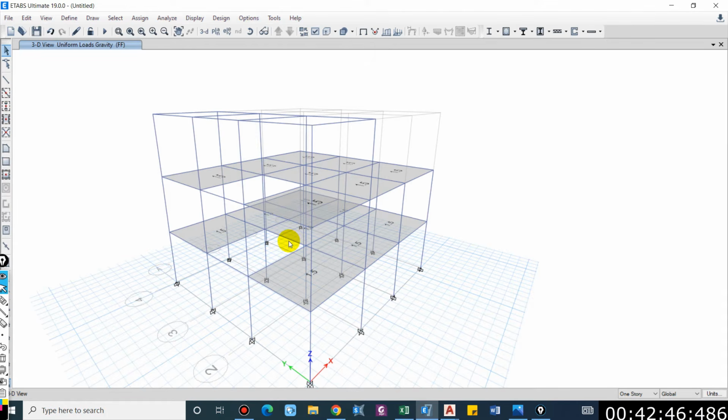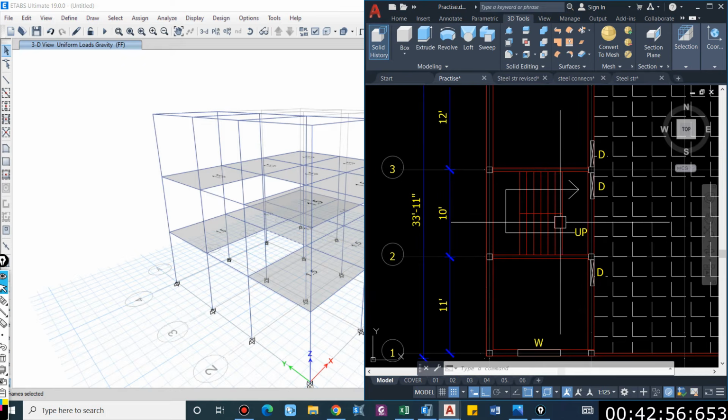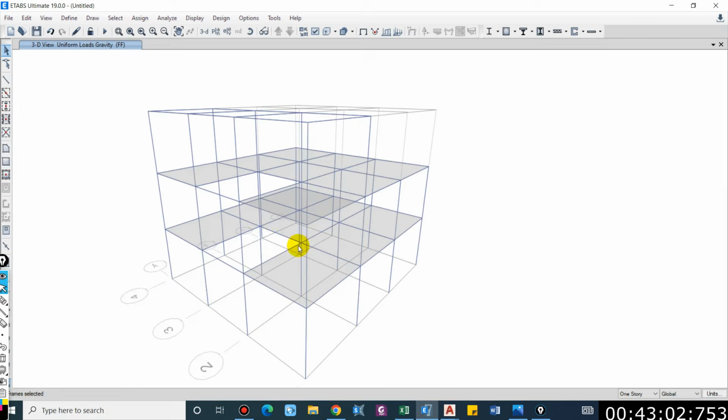You can simply find that. I'll take an approximate load for the stair. So for now, let us assume the dead load for this type of dogleg staircase as 22 kN per meter for 2 flights. That is, 2 flights are going to rest on this.